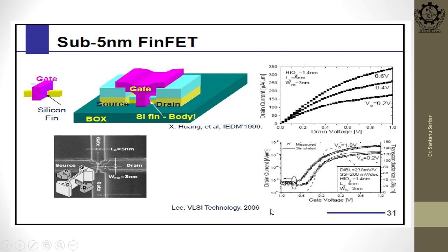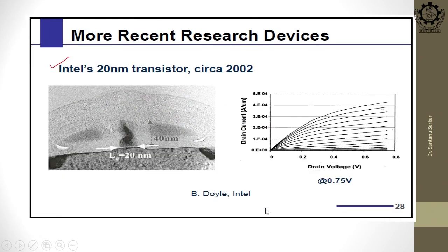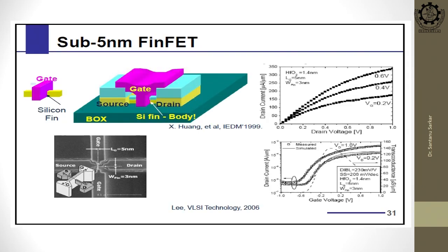To get better control for a very small length, what may happen is that the device can suffer from crosstalk. Adjacent voltage will introduce noise in your signal. Whatever your output signal is, if your channel length is getting reduced, it is difficult to have a tight control over the device. When you have a larger channel MOS transistor, you have better control and on and off are very well defined. But when you shrink your technology, a lot of crosstalk happens.